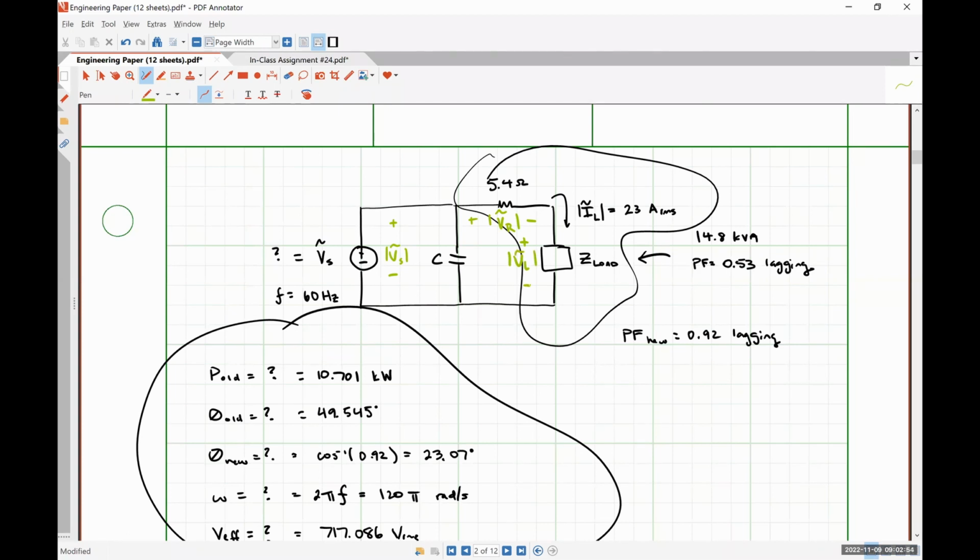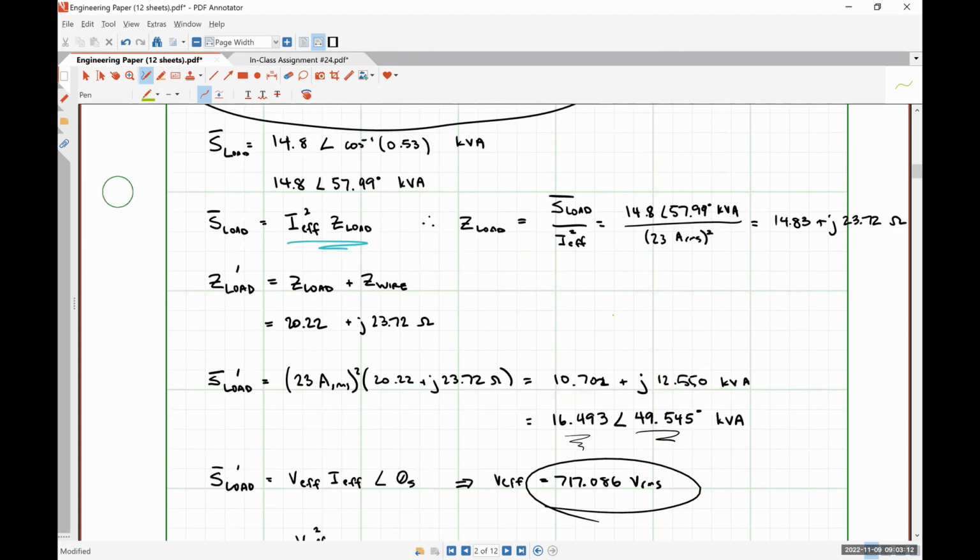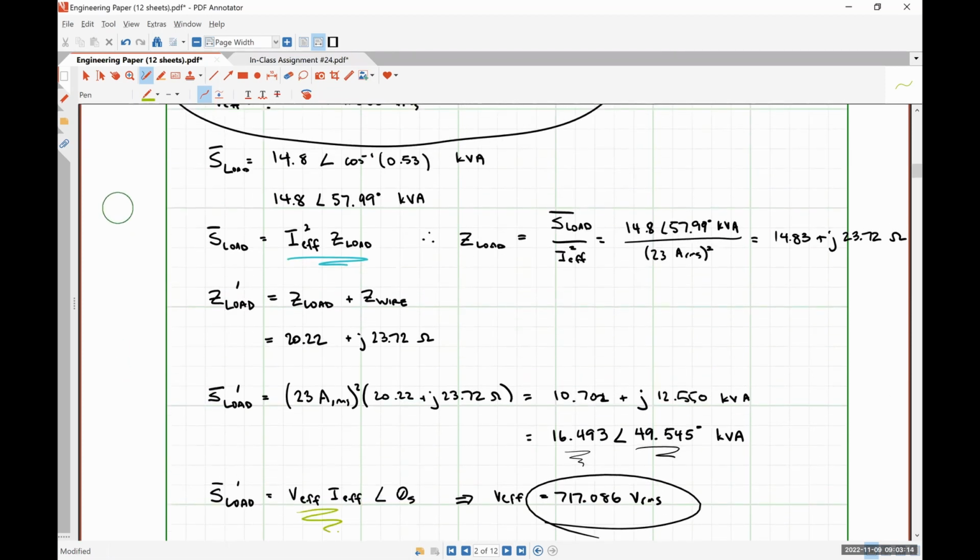That is wildly untrue. The magnitudes don't add together like that, because that's throwing away all of the phase angle information, which is not how complex numbers add together. So I just want to be clear about that so that when you calculate V effective, which I believe this is a perfectly reasonable way to do it, you actually get something that has some amount of meaning. Adding the magnitudes together does not work. So anyway, all right, so that's enough ranting out of me.